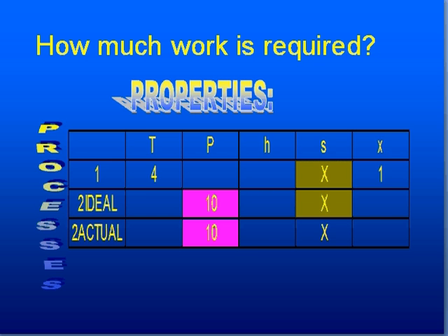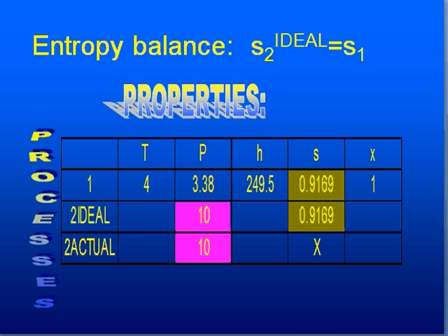The isentropic efficiency of 85% is a link between state 2 ideal and state 2 actual, and that allows us to find two properties about state 2. So we'll be able to calculate the entropy later and determine the entropy generated here as well. So the entropy balance then, if you plug in the numbers, you should get numbers similar to this.